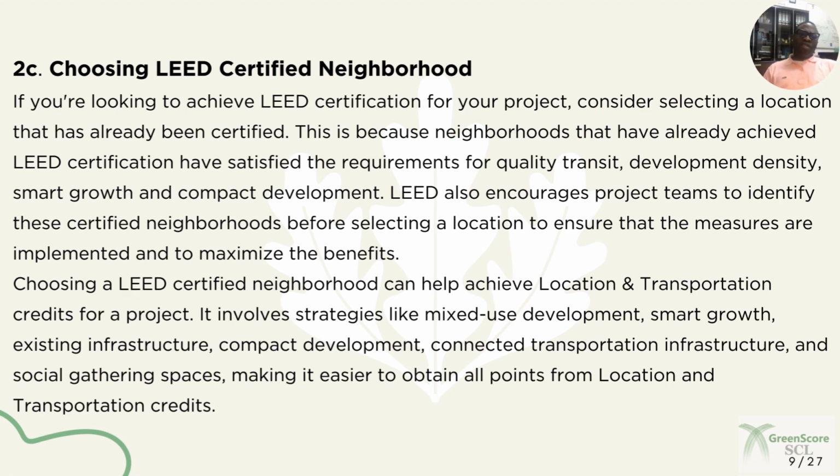Now, choosing a LEED certified neighborhood can help achieve the location and transportation credit for the project. Once the project is sited in an already LEED certified neighborhood, it is automatic admittance or award of the credit, and other strategies become irrelevant or unnecessary. All right, this is just like a one-way access to getting all of the points for that credit.